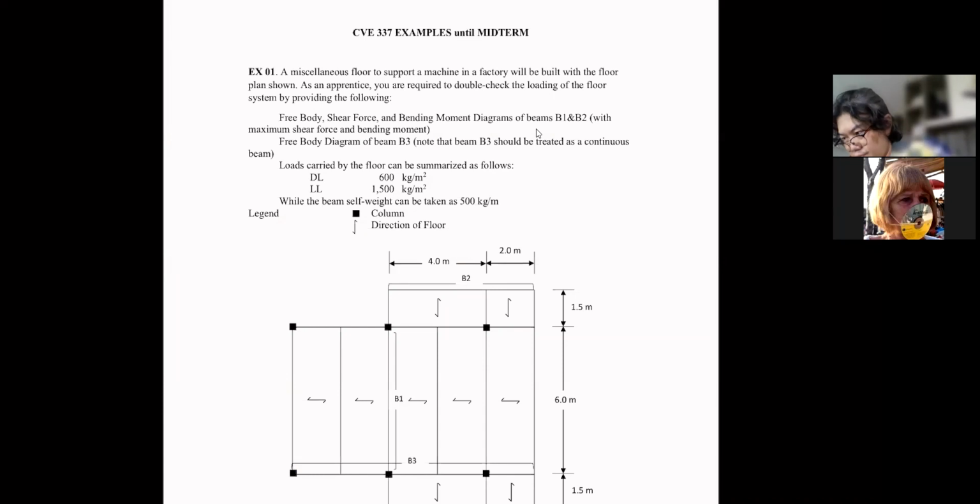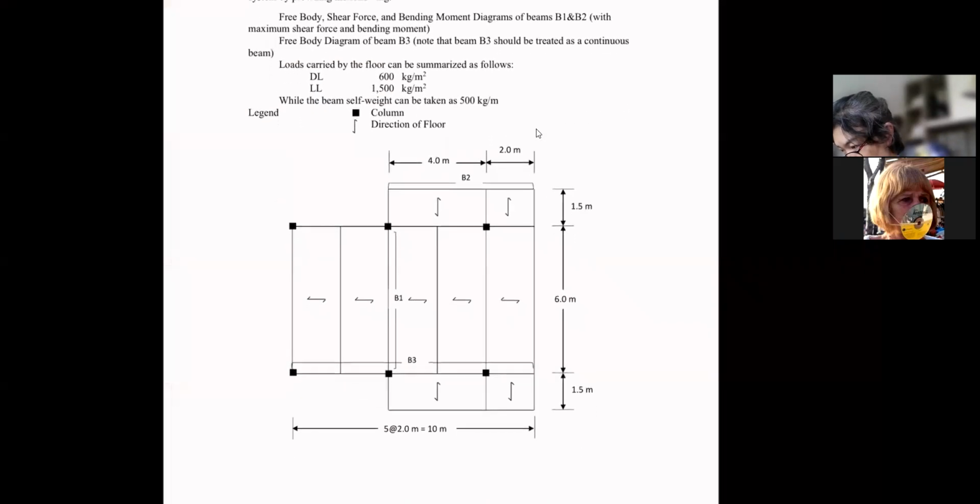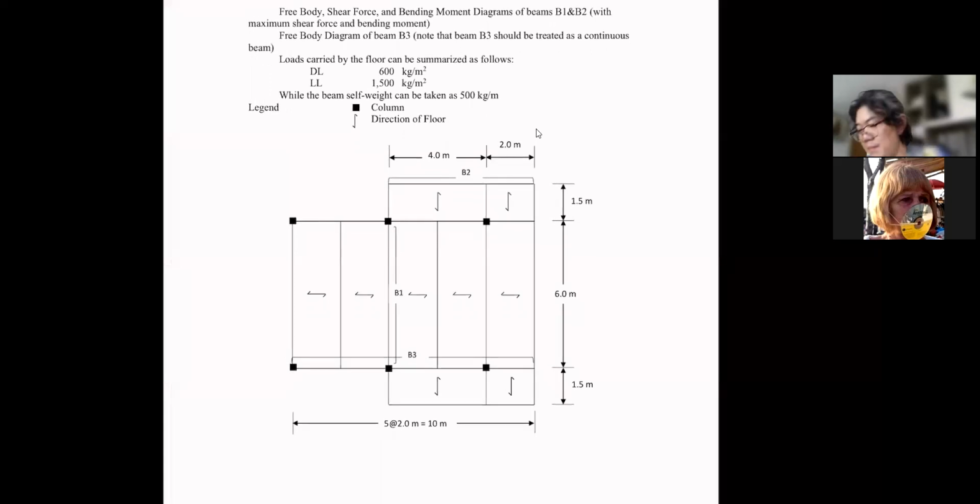So, okay. When we look at the system, I really don't think it's a good idea to call that one B1, because if you take a closer look, you see that this B1 will have to extend out and give the support to B2. When you look at the beam B2 itself, you see that it doesn't have the support.